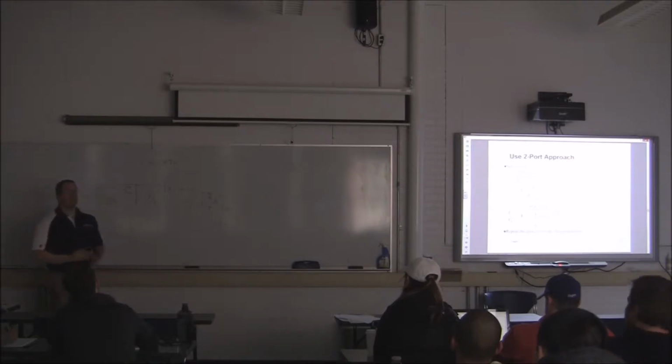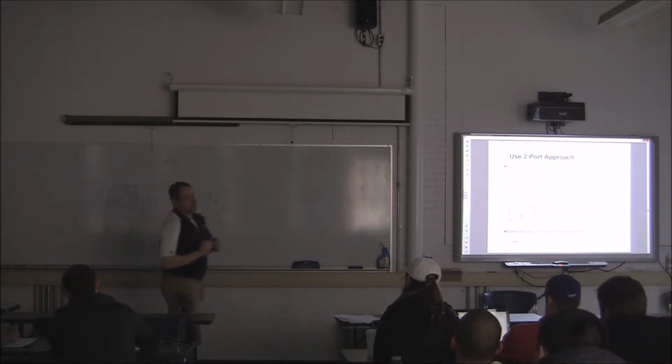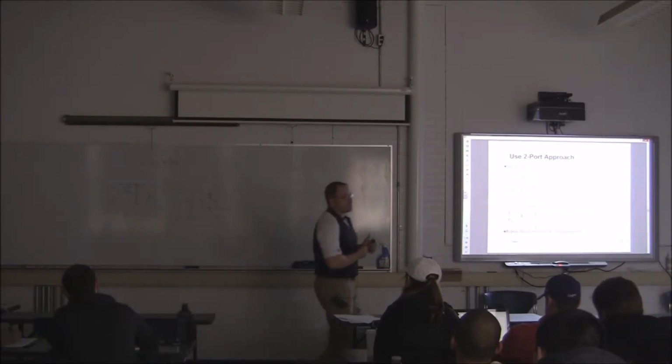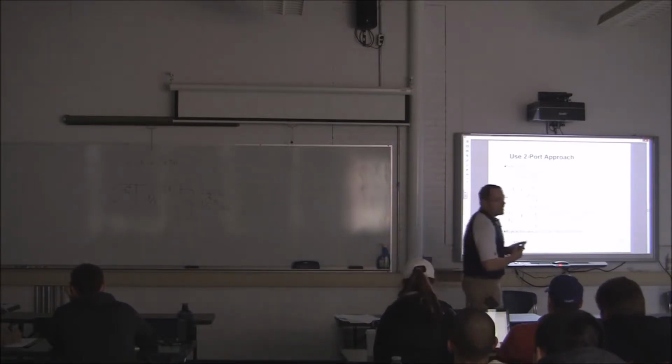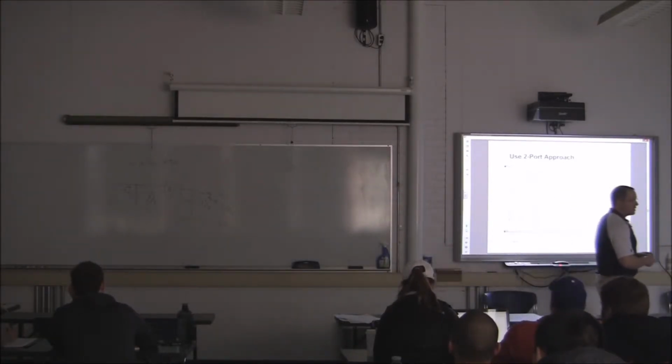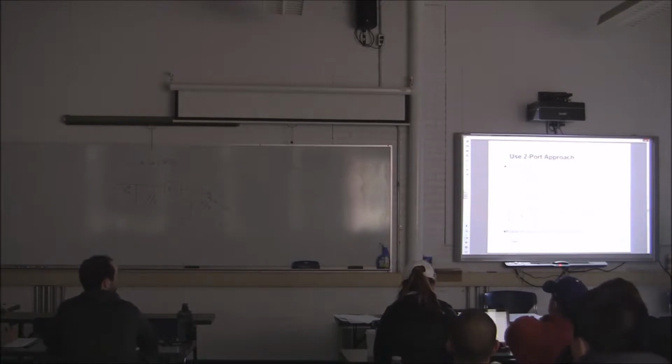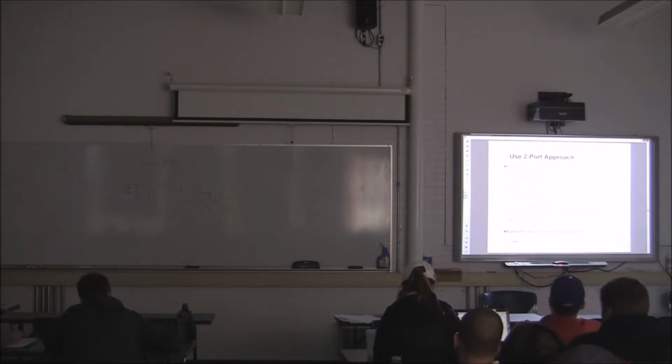This is a linear system. Linear system means if we can solve for any of the unknowns at any specific point on the curve, anywhere, then that will hold true for all conditions or cases. So let's use our heads for a second. Looking at that equation, VS equals A VR plus B IR, is there a way that you could get rid of an unknown?